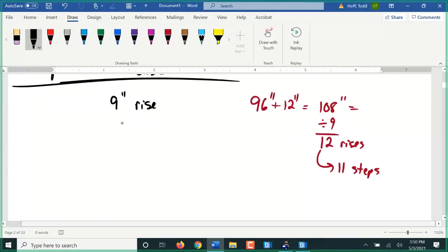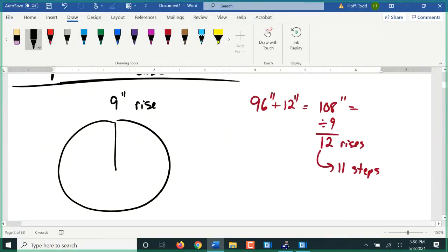If you do a spiral staircase, you have to have a minimum 90-degree landing. Now, that doesn't mean that the steps can't pass underneath that if you have enough height. You only need 76 inches of head clearance. So you can probably have a couple of treads that go underneath there if you really wanted to. Yeah, you could have exactly 2 treads going underneath there. That's awful tight.